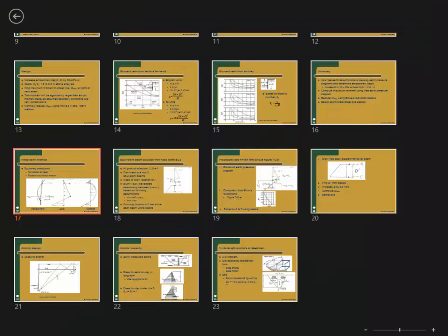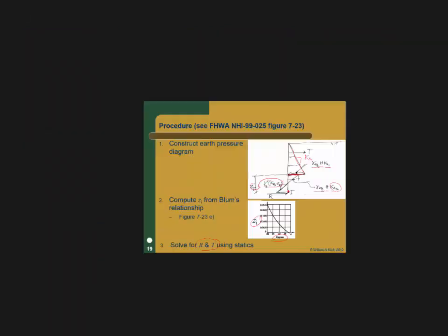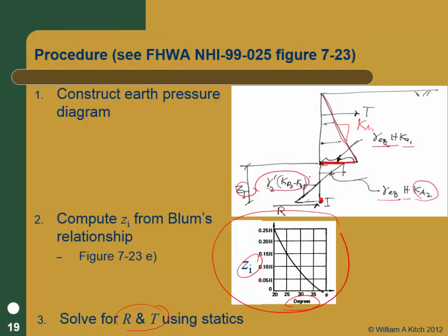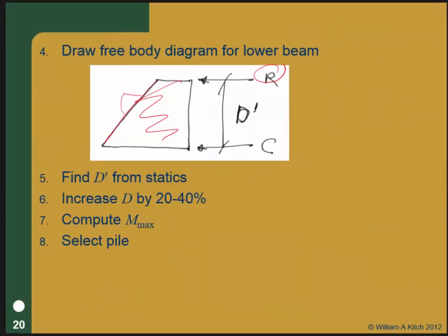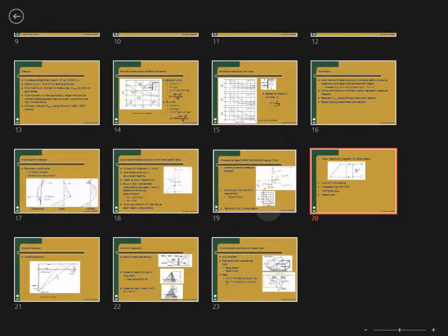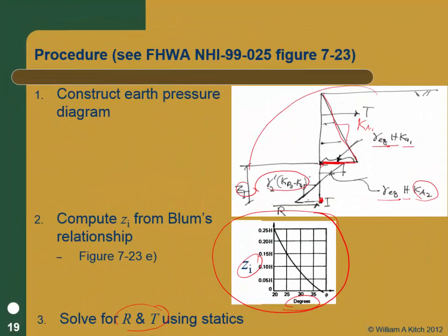And we can solve, and here's that approximation we're going to use to find Zi. And now we can solve, whoops, sorry. Once we know Zi, we can solve statically for the top equation. That'll give us the anchorage force, and it'll give us this reaction at the hinge point that we've assumed.